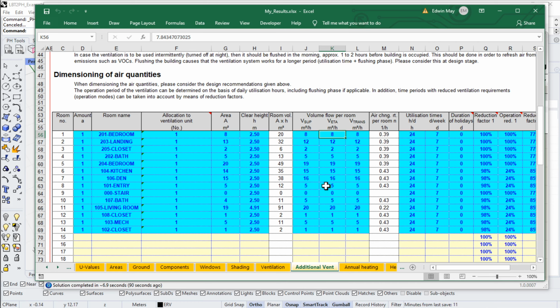It allows us to reduce our flow rates to a much lower level, improving indoor relative humidity in wintertime and summertime, and reducing those flow rates, so reducing energy loss and energy consumption, while maintaining really high indoor environmental quality. So that cascade ventilation approach can't really be captured by the standard Honeybee tools.